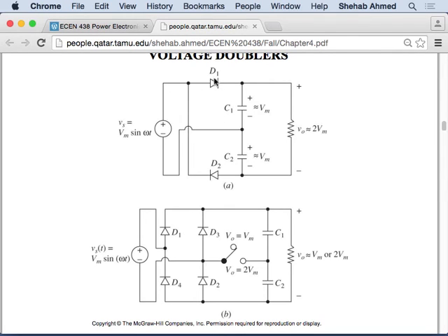What is it going to do? It's going to charge up this capacitor as well as what? Current will flow through here, back to this capacitor, back to the source, and this load is also connected, right? There's a circuit here as well, but current cannot go back from here initially. It cannot go back from here at all. It can go back from here, and what this will do is discharge this capacitor, which is initially discharged anyway. So maybe this capacitor voltage will go negative, not positive. It's going to push current in a different direction.